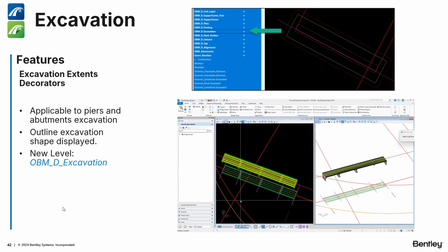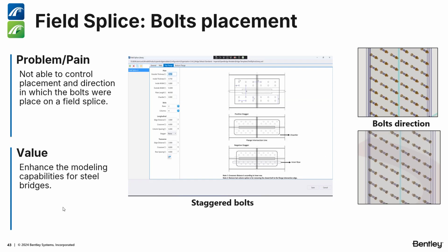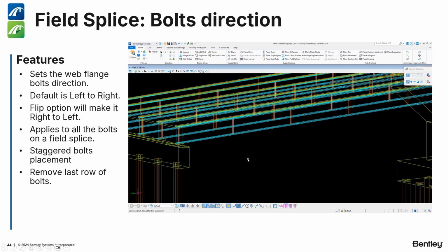For the excavation quantities, once you perform excavation, we have included the option with its own level to display the excavation outline as a decorator. For fill splices, we now have the option to specify staggered bolts along the fill splice, as well as the direction in which the bolt is presented in the 3D model.